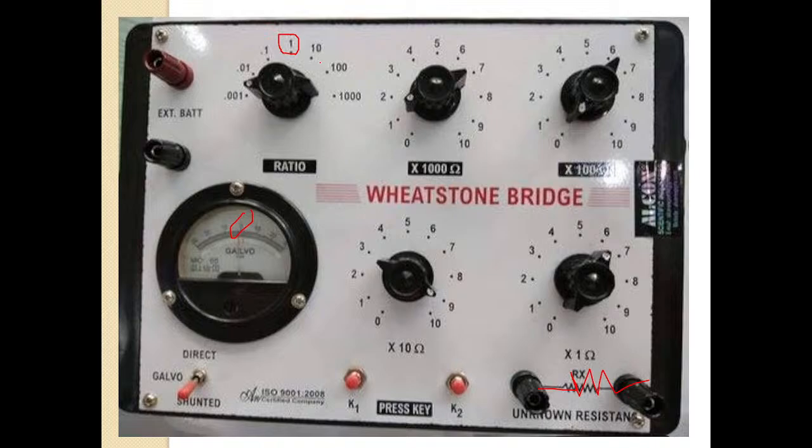So what you have to make sure is, once the galvanometer deflects, later on, as you gradually increase the resistance, the deflecting point should gradually move towards zero. It should not move away from zero. Based on which knob you are varying, because of the variation of which knob the galvanometer point moves towards zero, that you have to check.